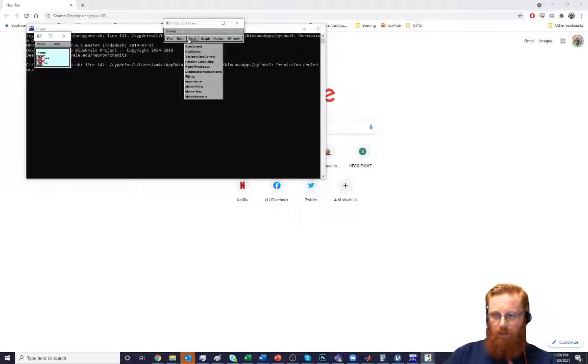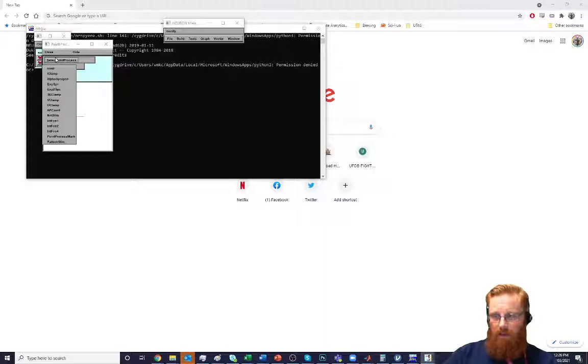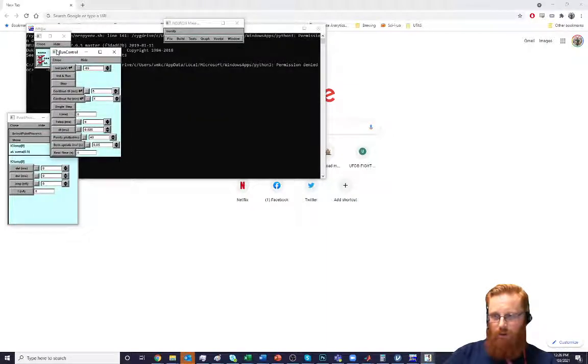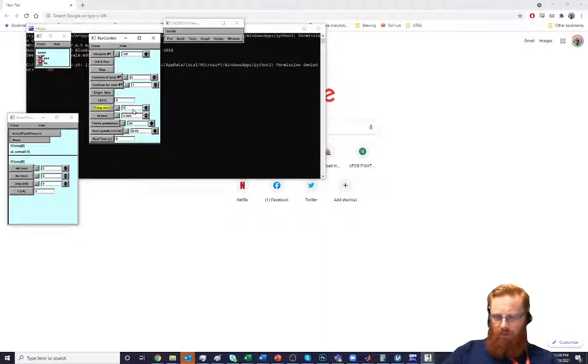and we might as well bring up a few things to make our lives easier. We're going to put in a current clamp electrode. And we might as well also bring up the run control. And we'll set t-stop to be something vaguely useful like that.